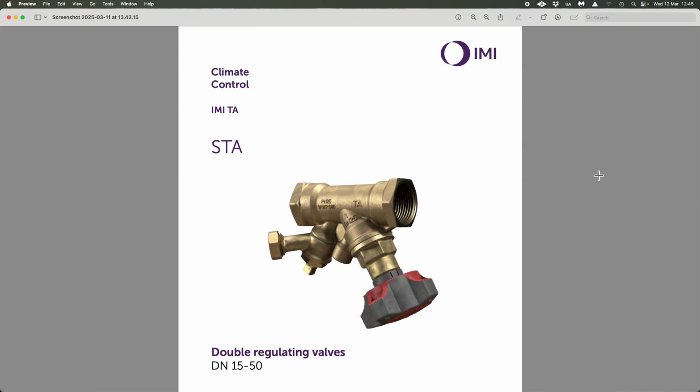And of course, as the water regulations state, we should never ever have any dead legs more than 150 millimetres long. That is the regulation. But of course, with all of these, we ended up getting lots and lots of dead legs, which is an issue with microbial growth. And what we started to find, I was getting clients there that were complaining, and these were generally elderly people that couldn't afford to upgrade boilers, so they wanted to stick with the original systems that they had.